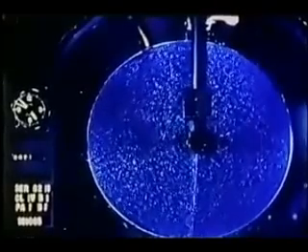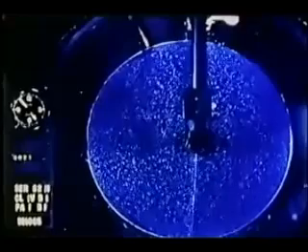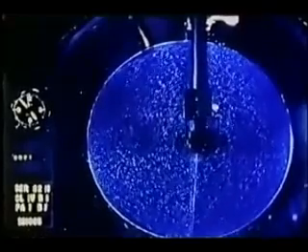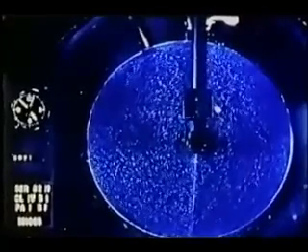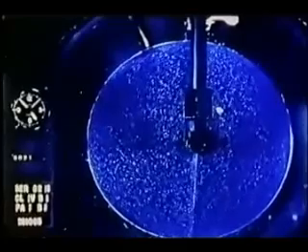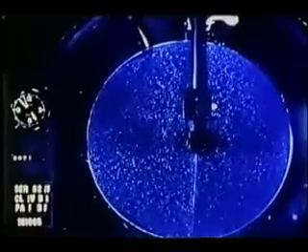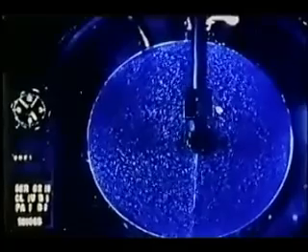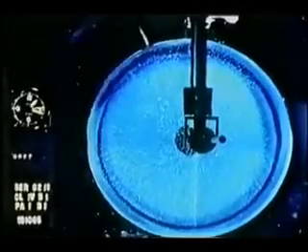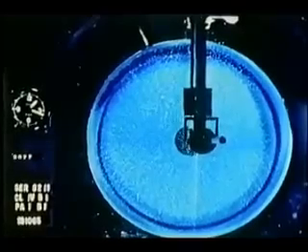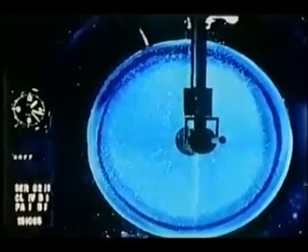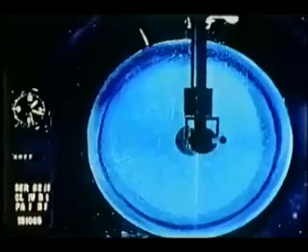The reason is that the rotational stability acts mainly against radial displacements. These become small relative to axial displacements as the rings decrease in width. We now increase the amplitude of oscillation. And you see the onset of one of the spontaneous instabilities.